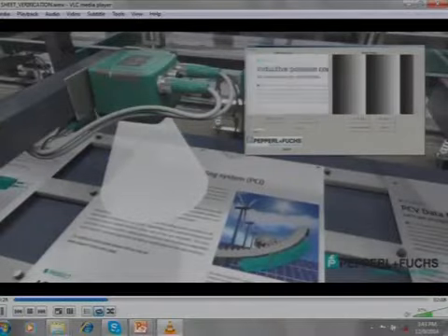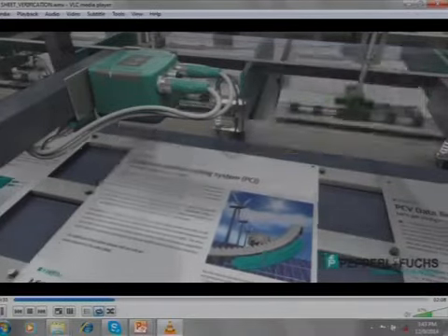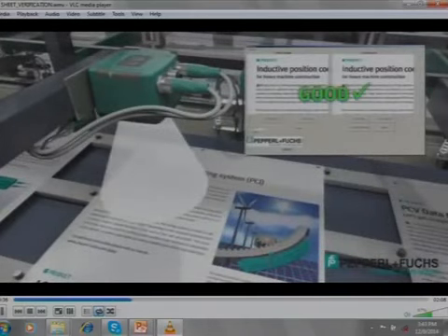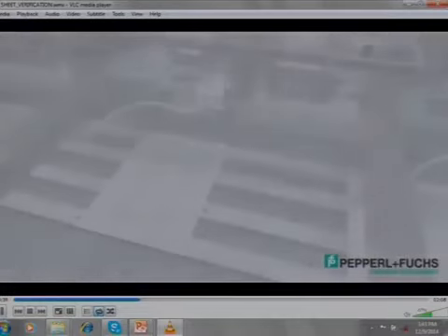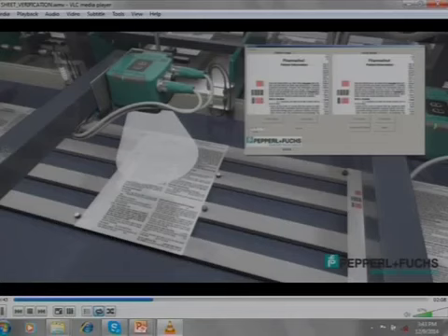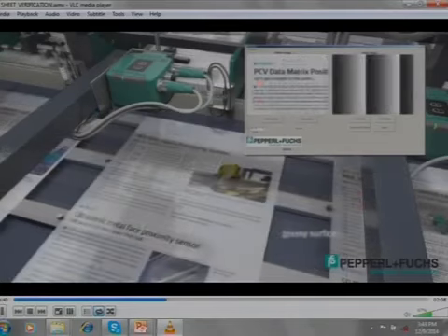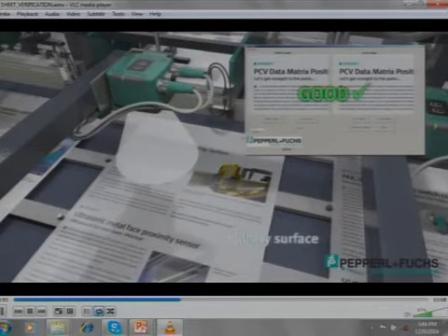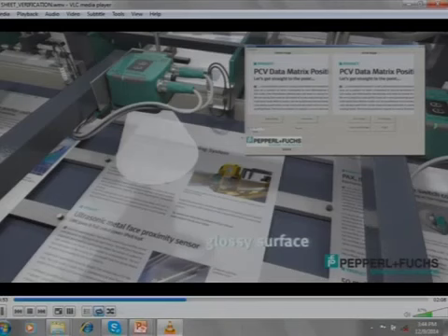So, now this is the pattern that has been taught to the camera. Every time this pattern comes, that means the stack is having the same paper. If there is a change in the paper, it will give a different output. So, it can distinguish between different styles, contrast values and paper. If both the images are the same, that means it is a good output, that means now the gripper can pick. The original picture in its memory? Is in the memory, yeah.